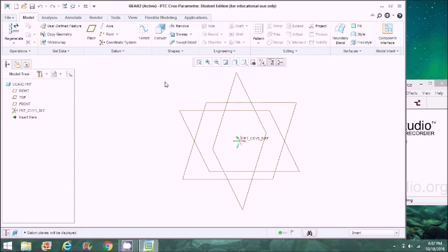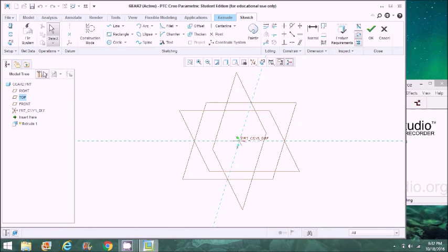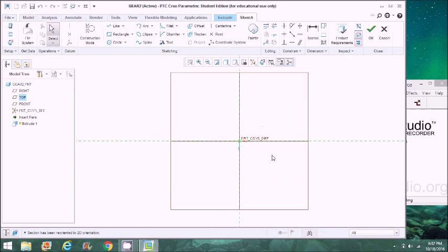First you're going to click extrude, and then you can click really any of these planes. I'm going to choose this plane. Any of them will work. Then if you go up to this sketch view button in the upper left hand corner, it will rotate it so it looks like you're drawing in 2D, which will be a lot easier to realize and figure out what you're doing.